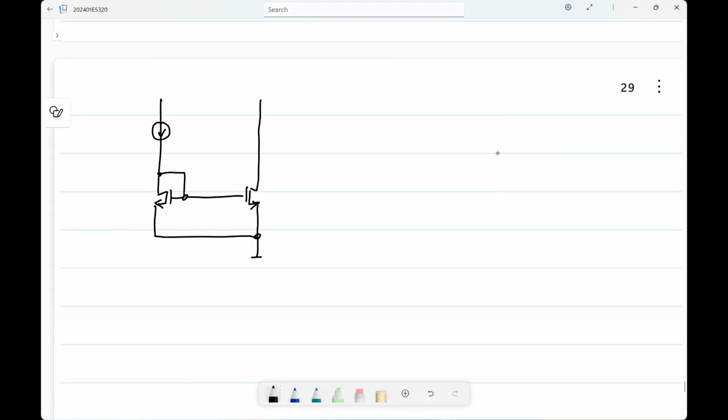So let's say I have this circuit and this is I naught. This is I out and I have a 1:1 current mirror. Okay, they are identical. Both have sizes W by L. So now I make this current mirror. These current mirrors are used very widely in circuit design. So what I want to find out is, again, my idea was that I'll get exactly the same current, but now we know because of mismatch it may not be.